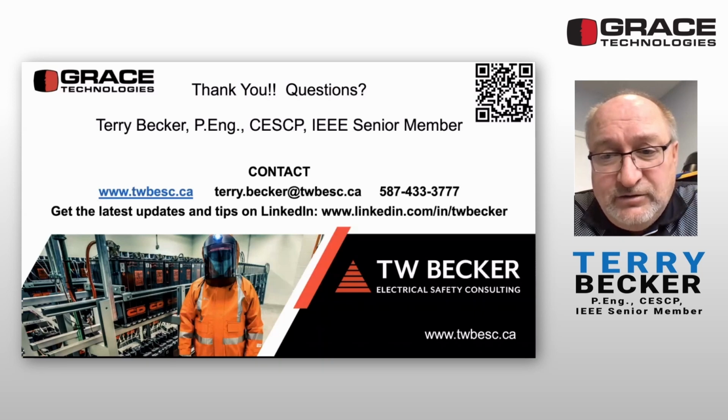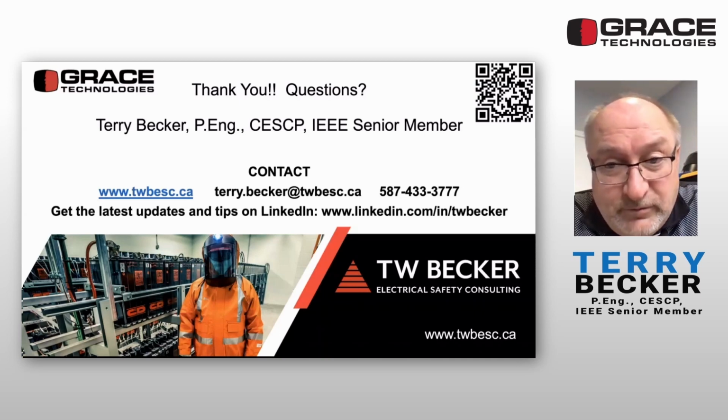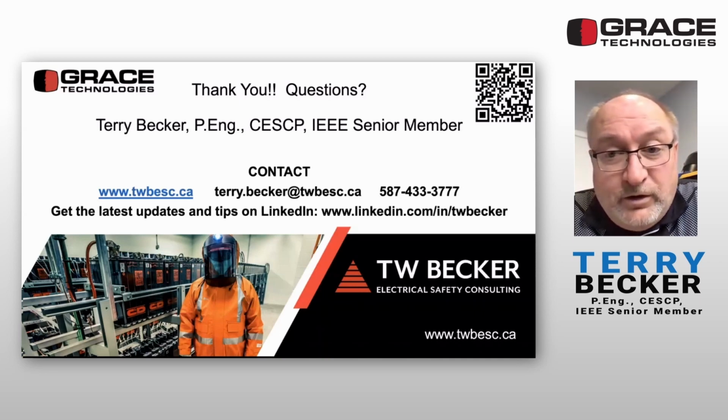Should the hazard communication be labeled or documented? Well, your electrical safety program includes a work task table, right? You do arc flash and shock hazard identification against the work task table, and then you do arc flash incident analysis studies and include labels on the electrical equipment where the worker may perform those work tasks.